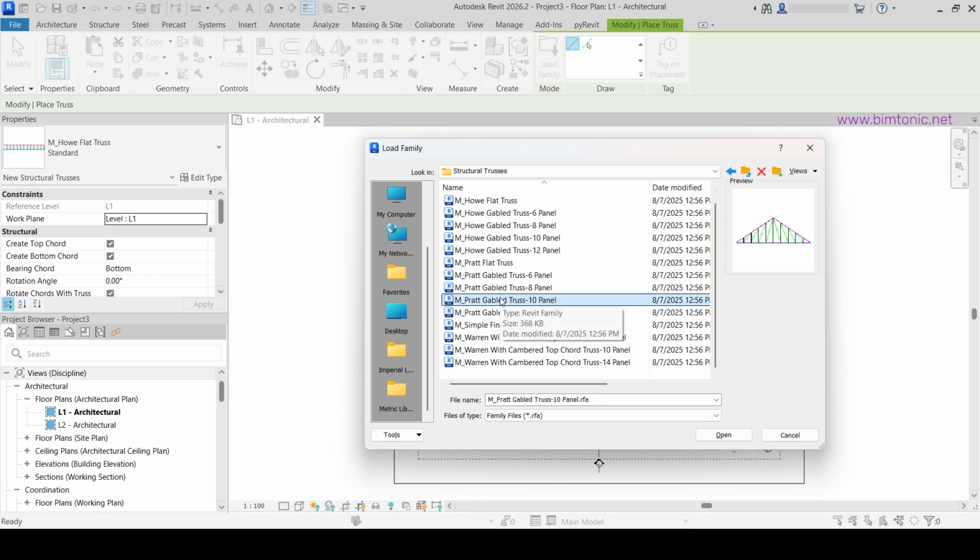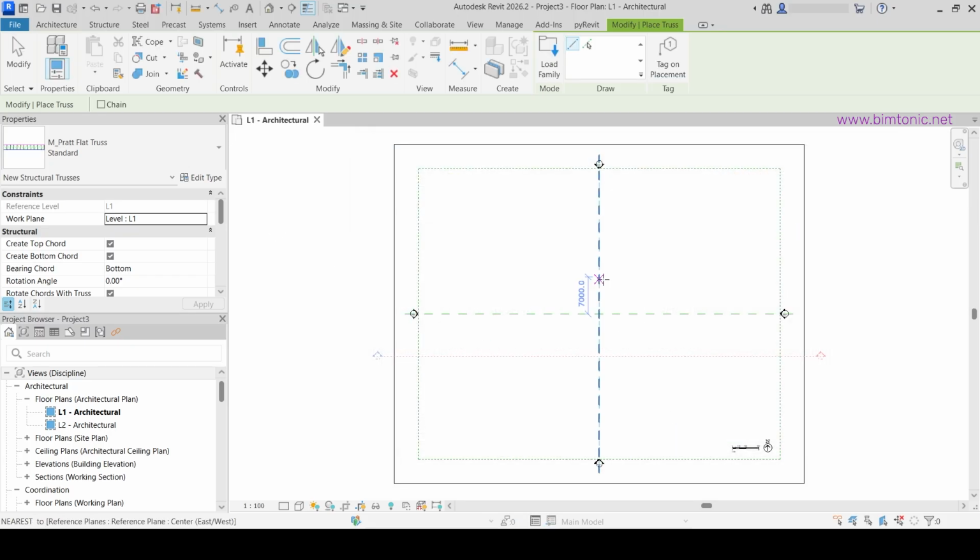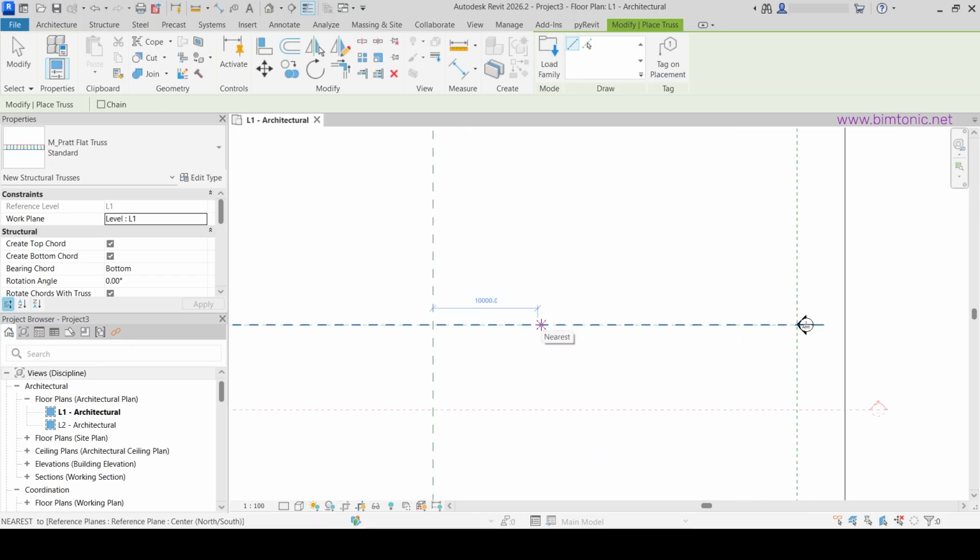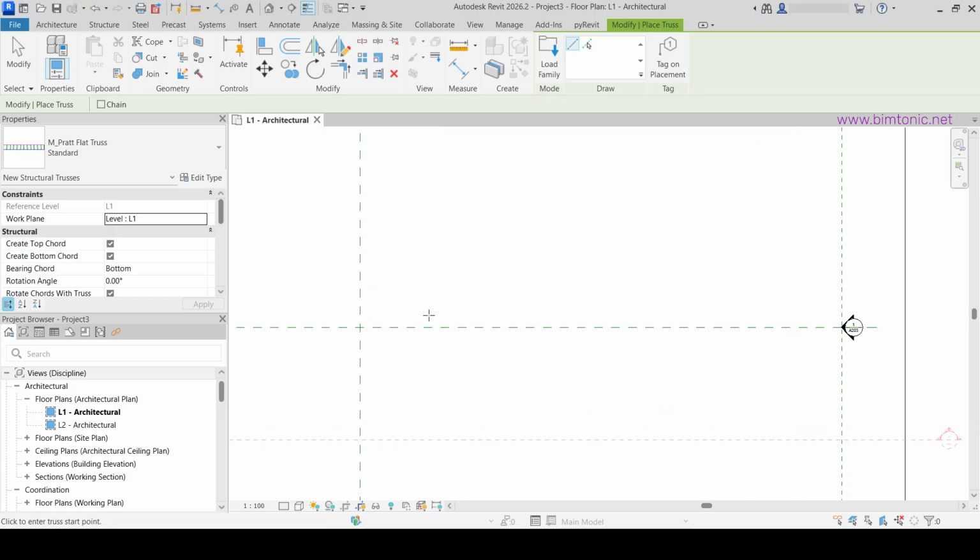You can also create your new one, which is also very easy, and in one of the next tutorials I will also explain that. But let's use some simple truss today. I will just load this one that already existed. And once it's loaded, first you have to draw it horizontally. So let's say I want the 10 meters long truss with, for example, 2 meters height. I would just click where I want my truss to begin and I will draw it to be exactly the length I want it. I see now here that it's 10 meters and then I click on that spot.